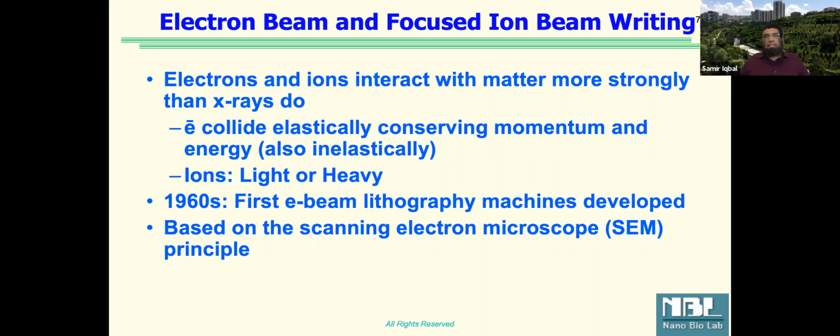So this is essentially the feature that we use in E-beam lithography, with an E-beam resist, same like you're using a UV resist, a photo resist, what we call a coating of material. So we coat a material that can undergo changes because of electron exposure. So we use electron beam.